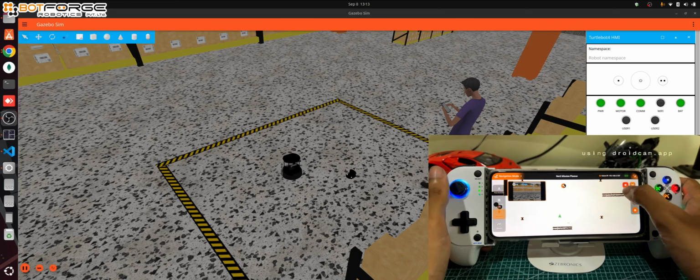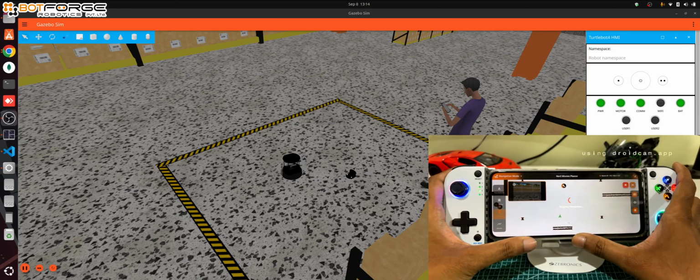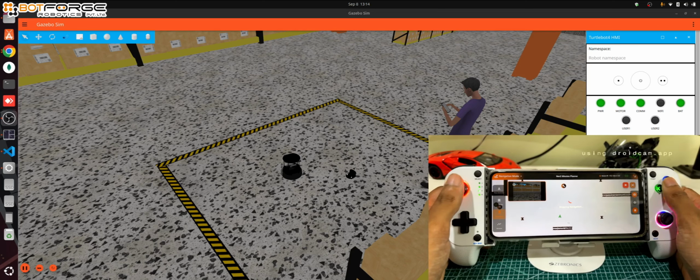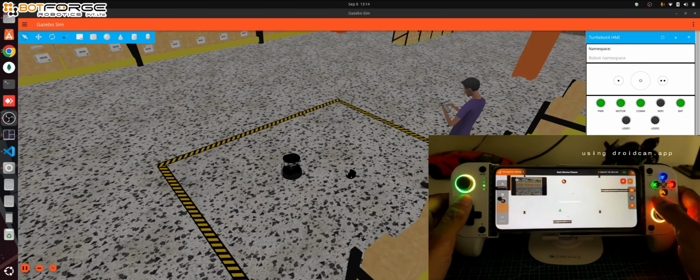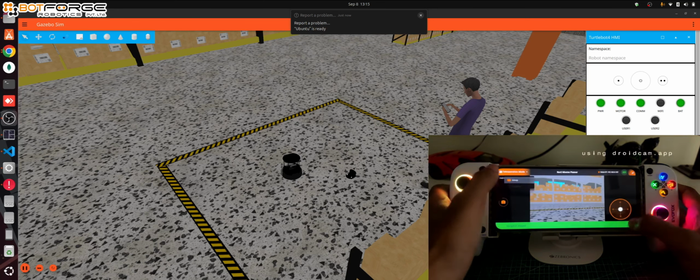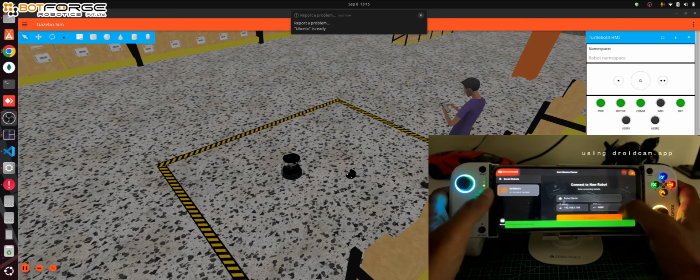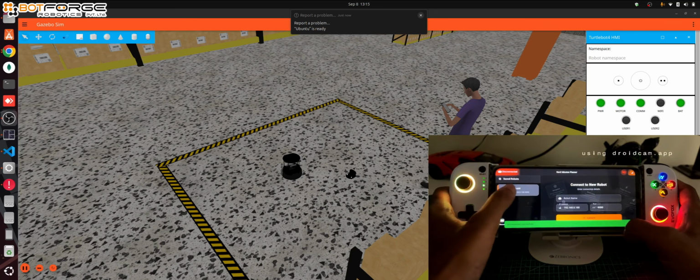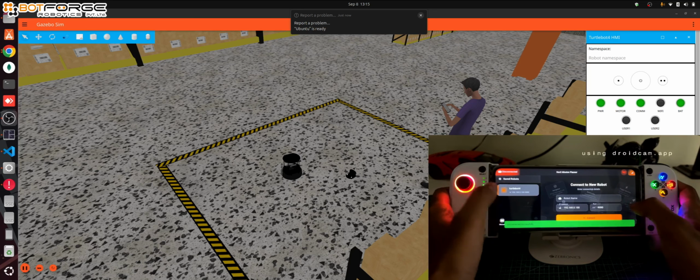Click on Stop Navigation. Wait for at least 60 seconds for all navigation nodes to completely close, as it depends on other factors. Then disconnect from the robot. On the left side panel, you can see recent robots. Slide left on any robot to delete that robot, or you can add a new robot from the right side.